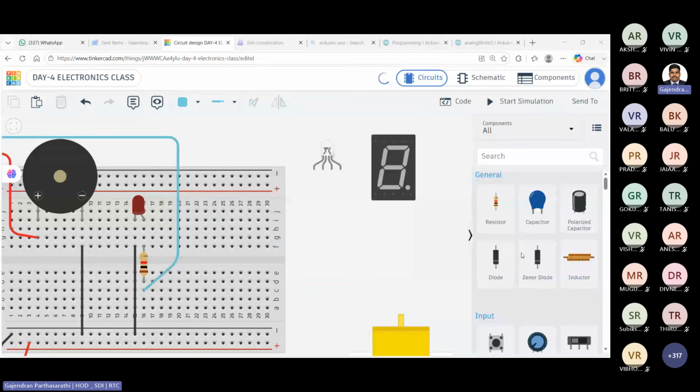What is meant by motor driver? Darshan, motor driver means very simple. Our microcontroller is capable of driving only very small currents. For example, 20 milliampere only maximum it will drive. If the current rating is more, we need to go with driver circuits. Tomorrow we will teach that.